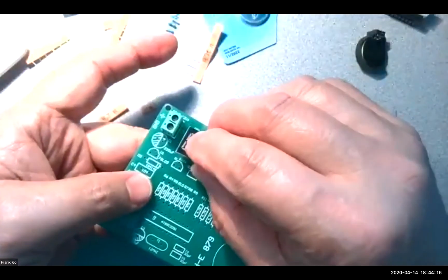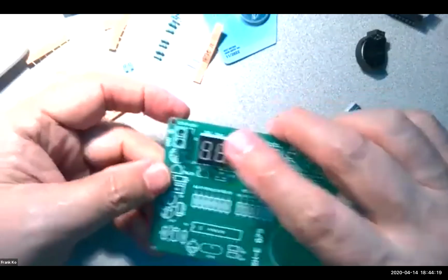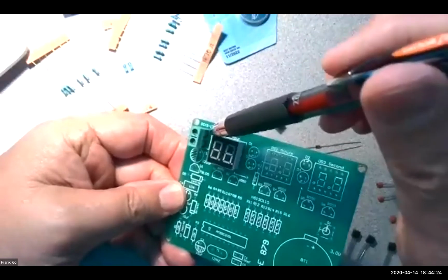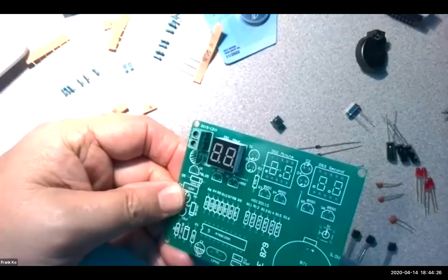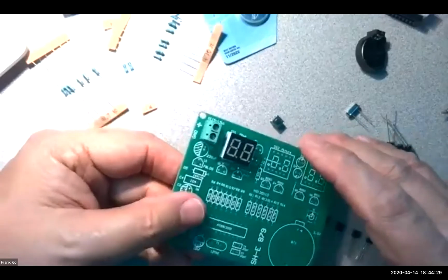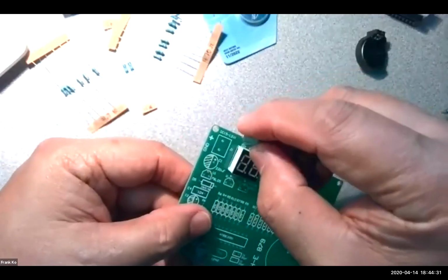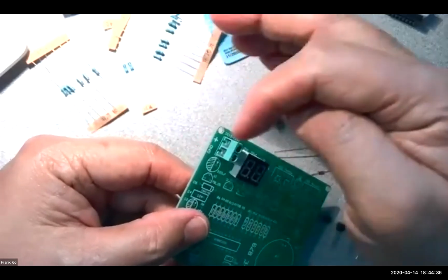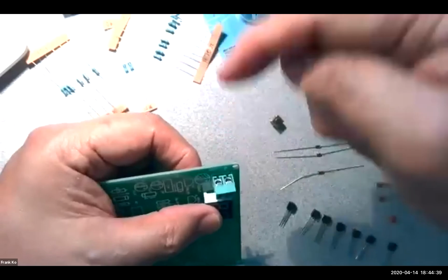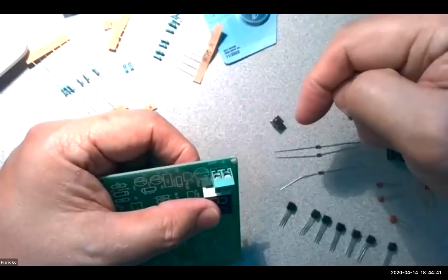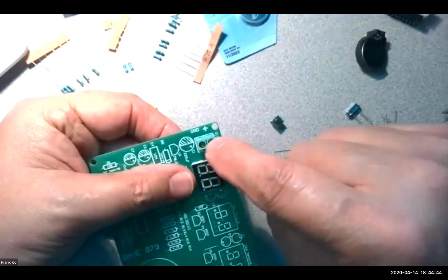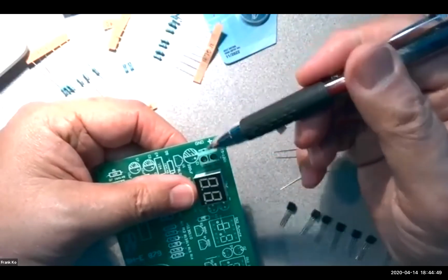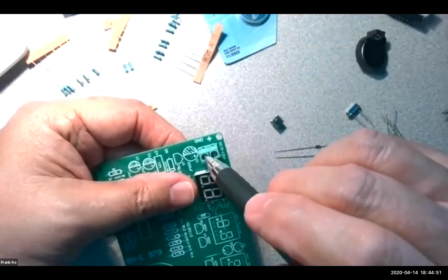There's going to be a ginormous LED that's going to sit right here, a numeric LED. If you wire it this way, won't it be incredibly awkward to get a wire into that terminal? That would be not so bueno. So you want to make sure the screw wire access is facing the outside. This way your wires can come in without any obstruction, and then you tighten down the wires here and here. Your battery pack will have the positive attached to this terminal and the ground or negative attached to this terminal.